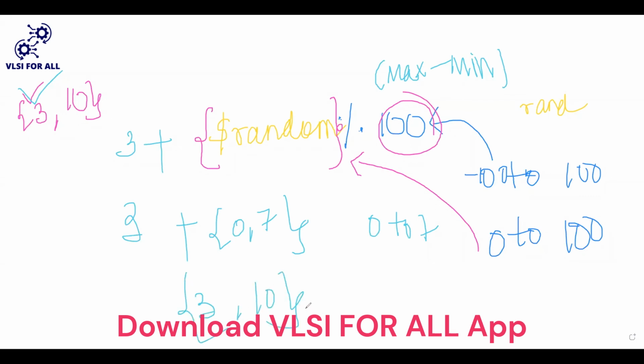This problem has been overcome in SystemVerilog by using $urandom_range. We can directly specify the range. So this is generating the random values.